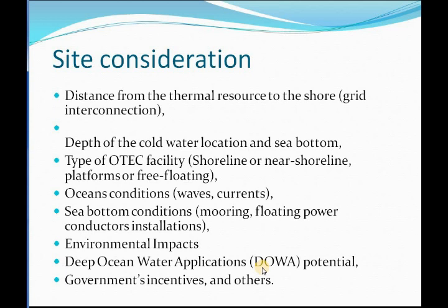Okay, the next we are seeing is the cold water location or the depth of the sea. Okay, the sea water where you are getting a temperature difference of 20 degrees between the warm water and the undersea cold water, the temperature difference should be 20 degrees. But how deep is it fine to go? See, for a temperature difference of just 20 degrees, if you go much deeper, that will increase the installation cost as well. So you will select a place where the depth of the cold water location is not very deep.